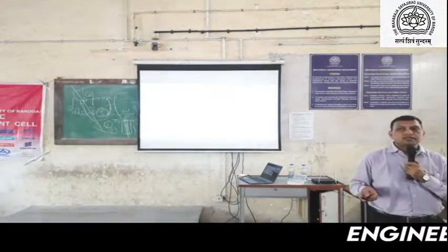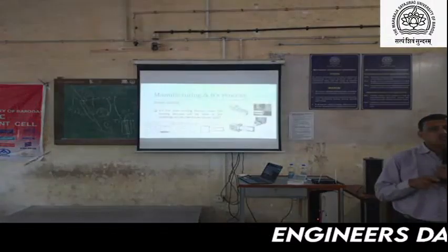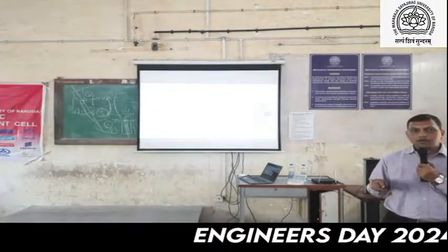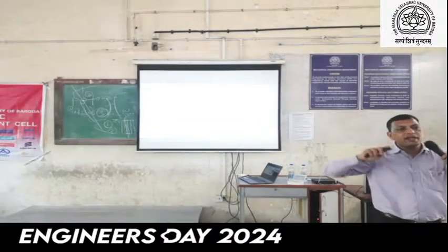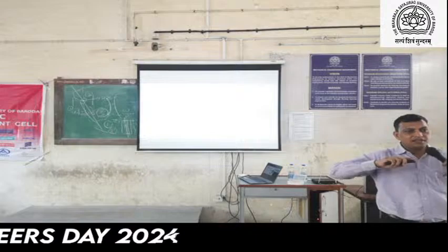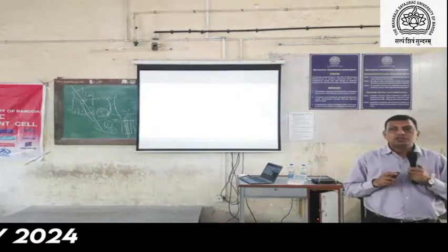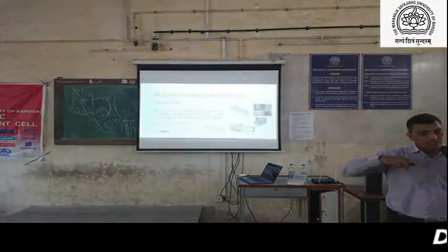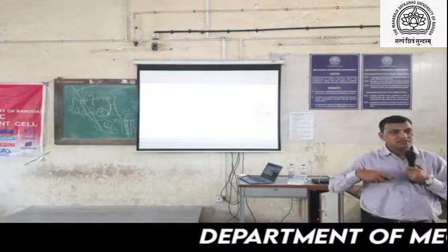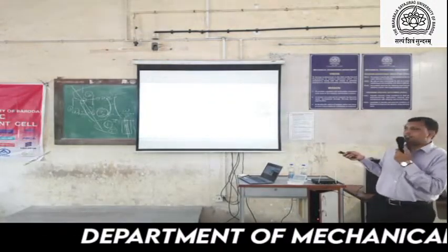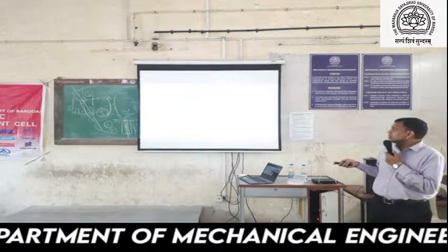After heat treatment, there is some chance of distortion of the material. If there is a long shaft, it can be bent or slide due to heating. So that should be straightened, and then the final finish form is finalized. That should be considered in the finish turning.